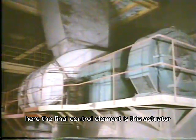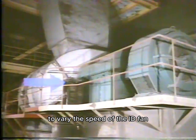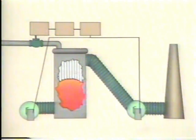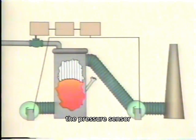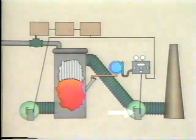Here, the final control element is this actuator, which adjusts a hydraulic coupling between the ID fan and motor to vary the speed of the ID fan. Let's go back to our illustration of the process to see how this control loop works. The elements of the control loop are the pressure sensor, the transmitter, the controller, and the actuator.